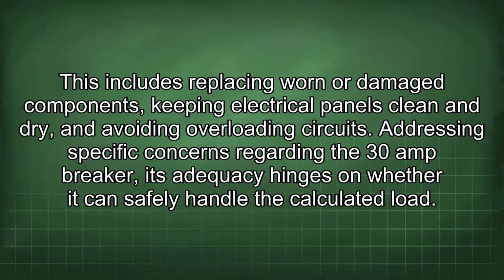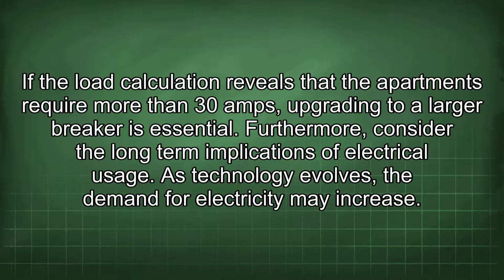Addressing specific concerns regarding the 30-amp breaker, its adequacy hinges on whether it can safely handle the calculated load. If the load calculation reveals that the apartments require more than 30 amps, upgrading to a larger breaker is essential.